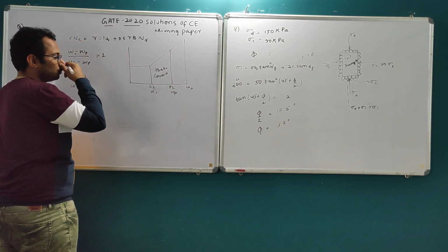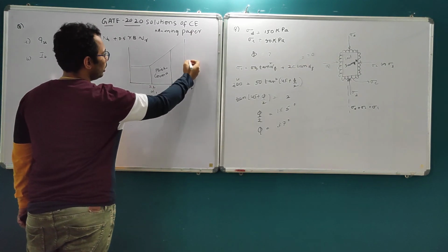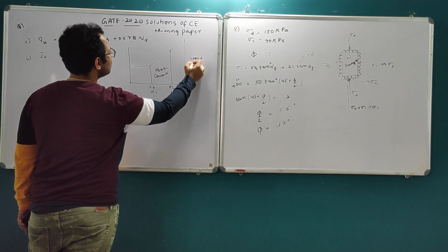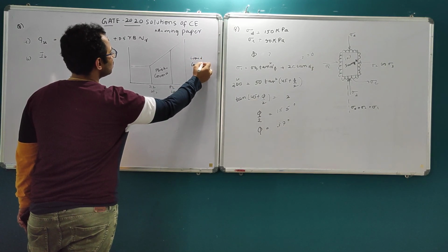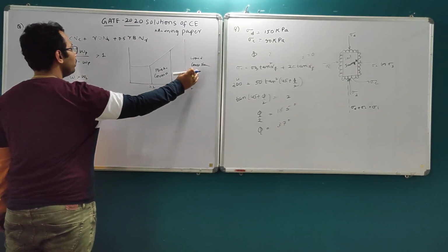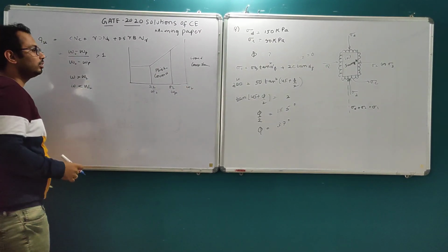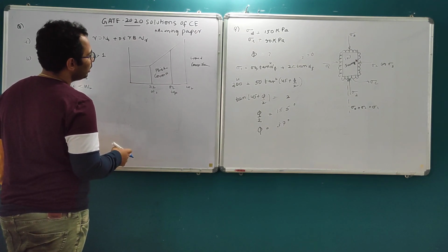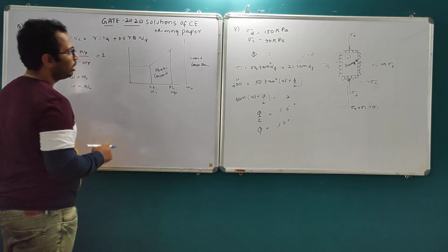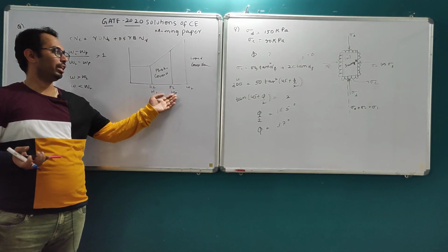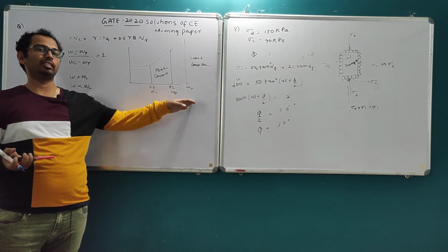Okay. So here, if this is the location, he is saying here it is in liquid consistency. So how can the soil be in plastic consistency? Plastic consistency will be present in between these two, up to the plastic limit. Beyond the plastic limit, it attains a liquid consistency.